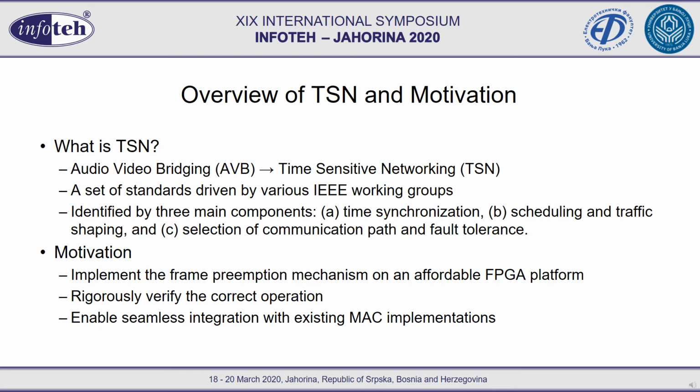So first thing we want to discuss is actually what is TSN. TSN is short for time-sensitive networking, which is an evolution of previous standard called audio-video bridging, or AVB. It is actually a set of standards driven by various IEEE working groups, which can be identified by three main components. Time synchronization is the first component, which is responsible for maintaining the common sense of time for every device in the network.